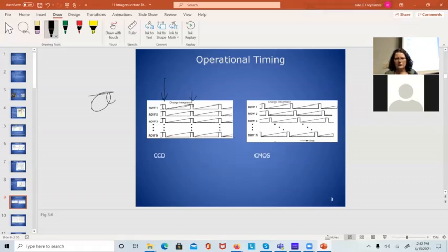Now, the CMOS imagers, because it's built in a CMOS process, standard CMOS, instead of the special process for CCDs, we can put all kinds of CMOS electronics in there, any kind of digital thing you want. We had random access, and what we would do is we'd go in and reset row 1, and then we'd reset row 2, and then we reset row 3, and we would wait a row time between the resets, so we could actually interleave these later.